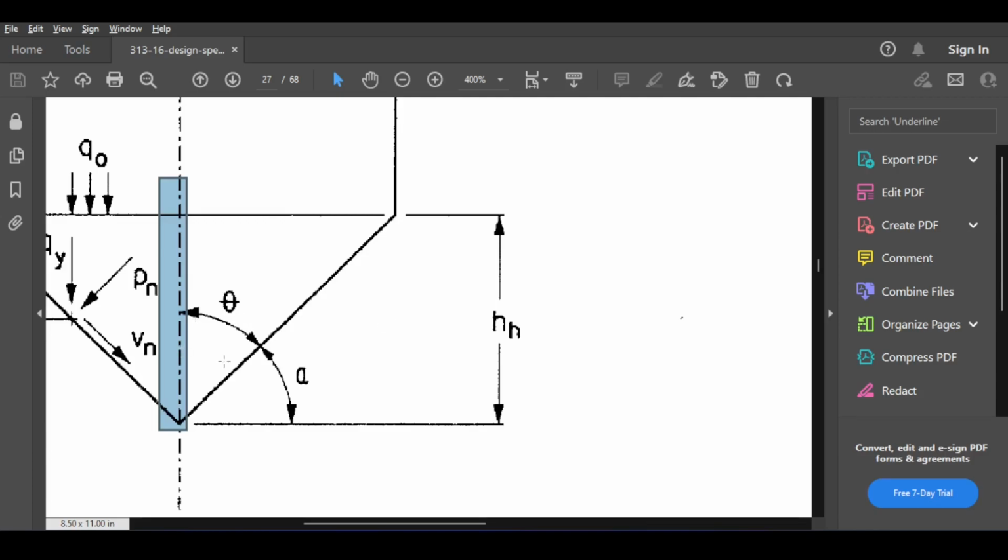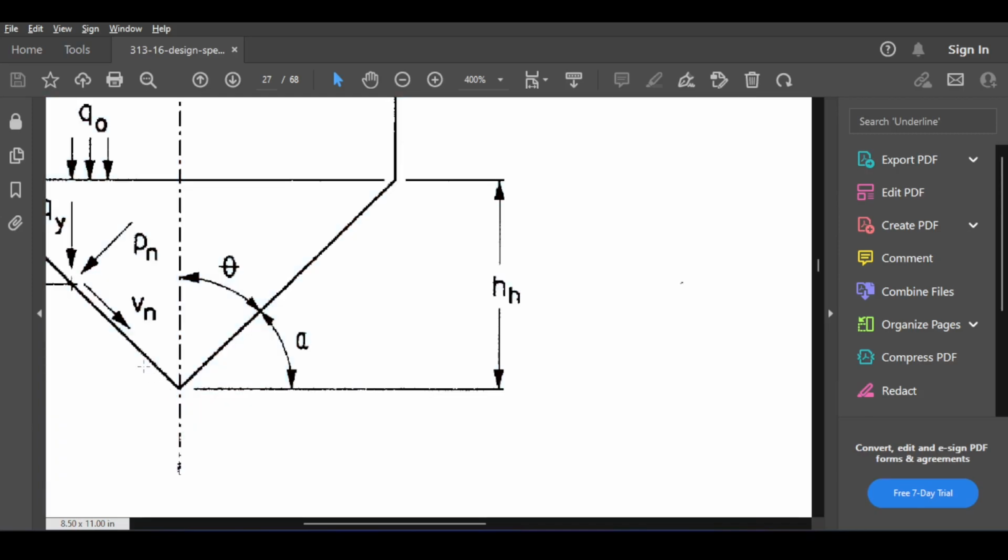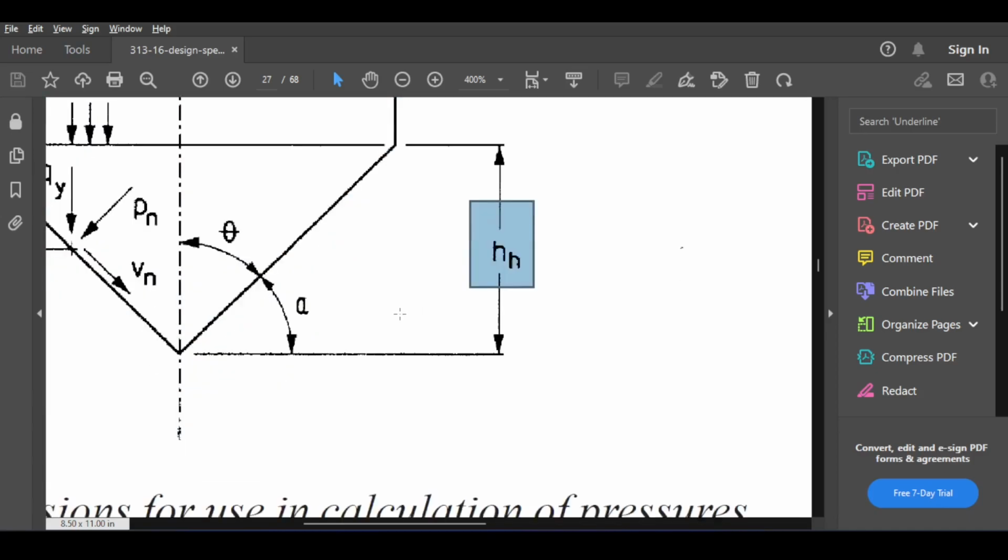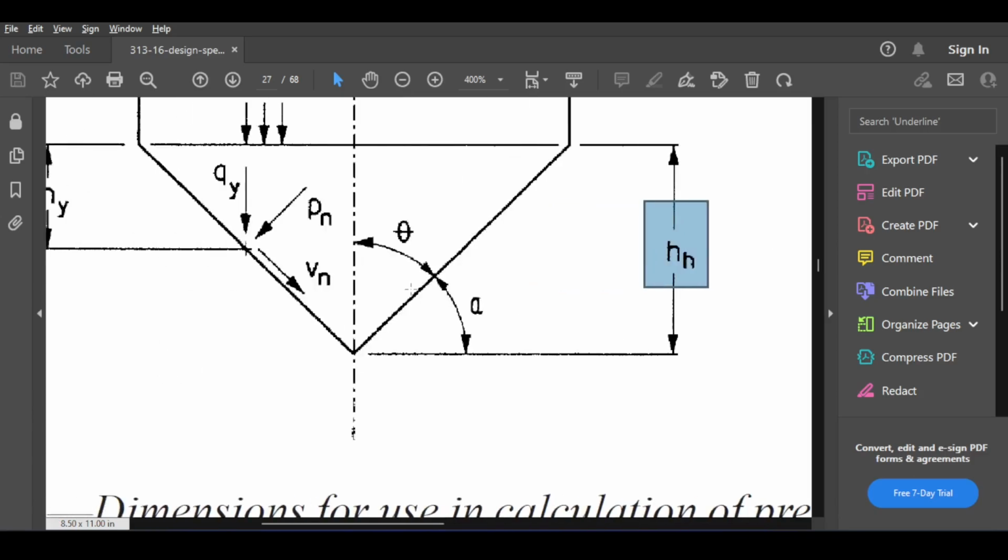It could be different. There is, of course, a simplification to notice that usually you have an opening here. So for the true theta, you will notice that there is an opening here. So your phi should not be basically half width over h in tan inverse. No, it should be the half width minus half opening divided by the height of the hopper. And that's correct. Truth to be said, you hit the nail on its head, so yeah, that should be done.